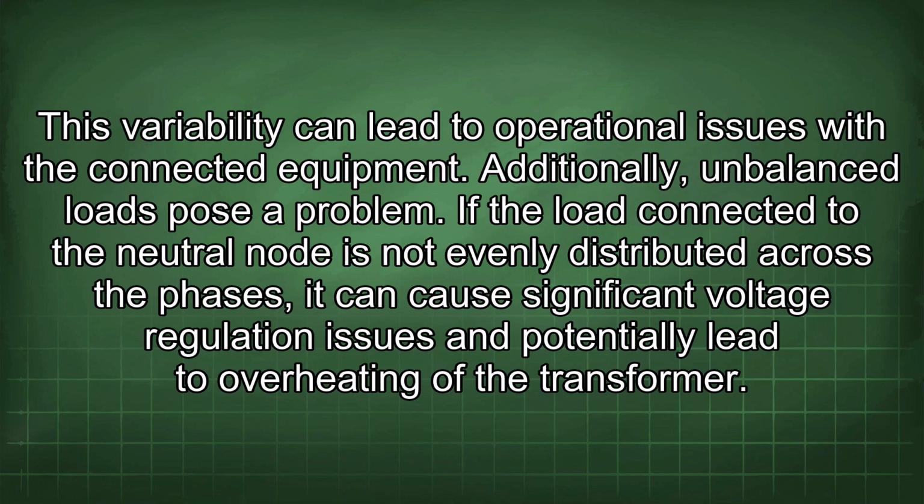Additionally, unbalanced loads pose a problem. If the load connected to the neutral node is not evenly distributed across the phases, it can cause significant voltage regulation issues and potentially lead to overheating of the transformer.